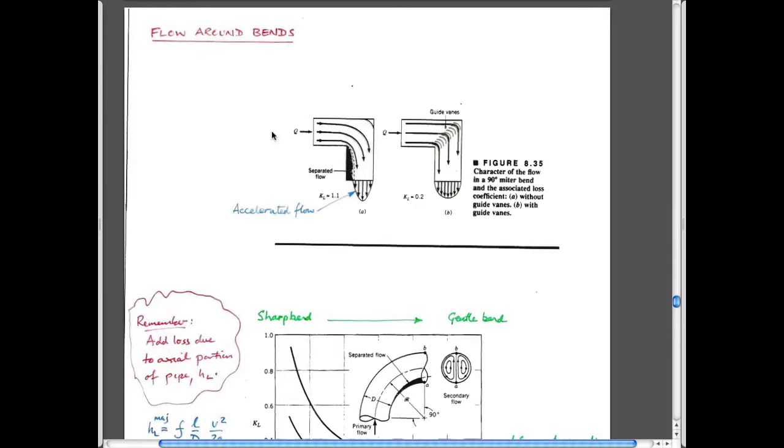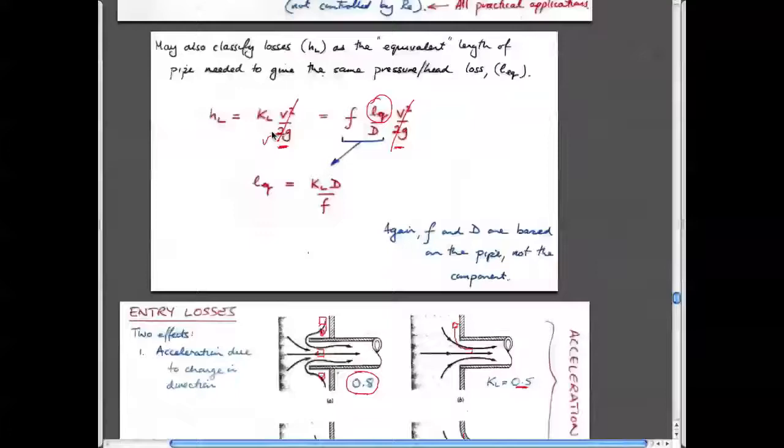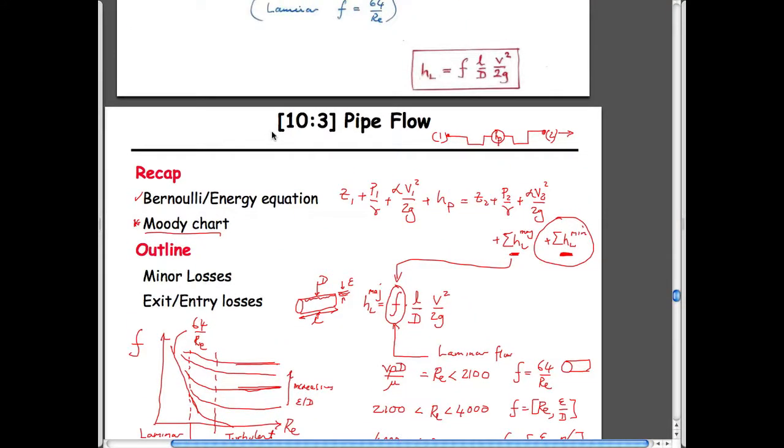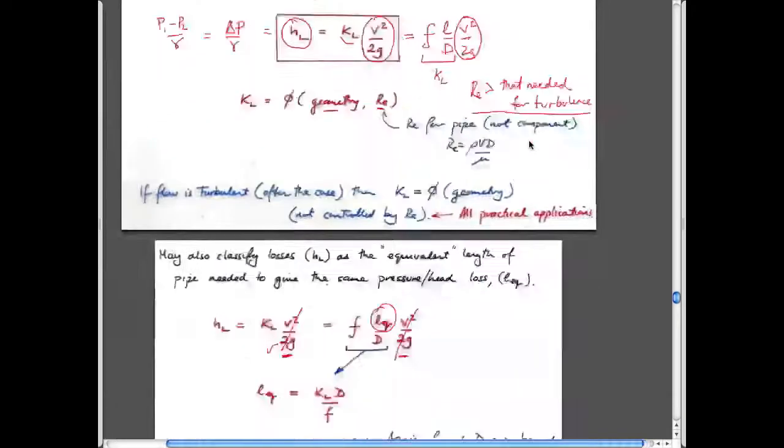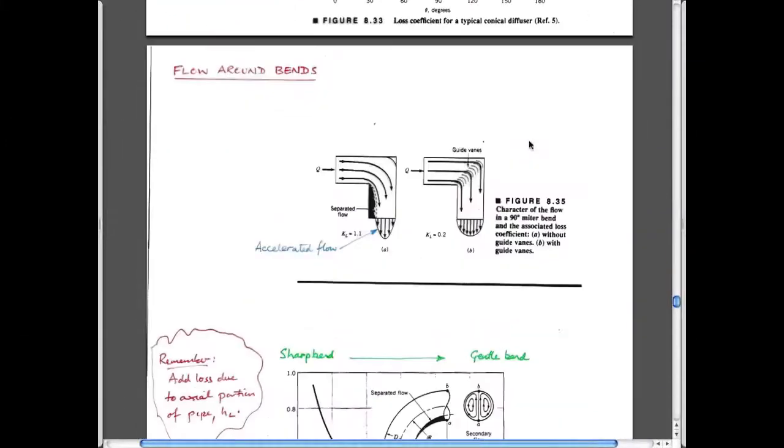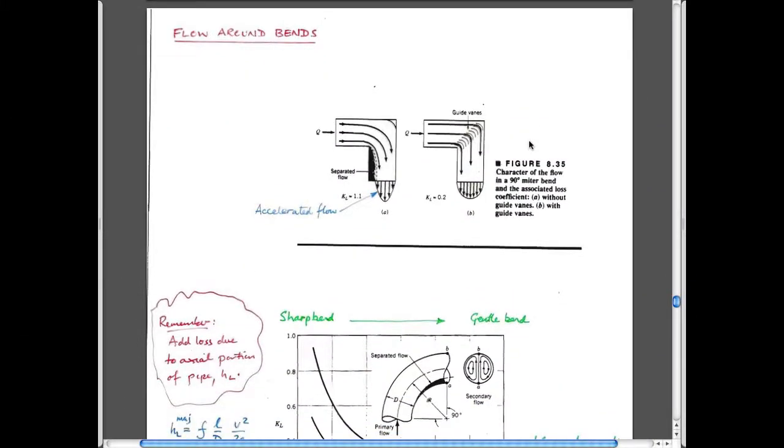The other more usual behavior is to look at the response you'd have as you go around the fittings. So I've deliberately drawn this here with these magnitudes of the minor losses. But the other features you have, in addition to inflow or exit losses, which of course would occur at these points if you had them, then we have to worry about what the magnitudes are as you go through individual fittings. And again, it's just a recipe. And so you need to go to whatever charts your book has in them.